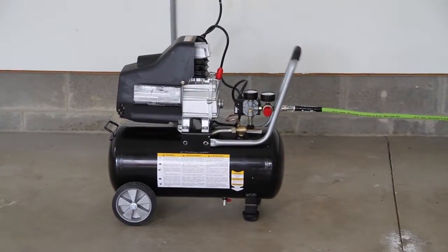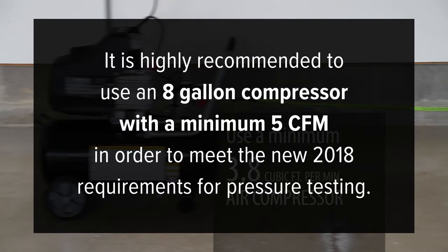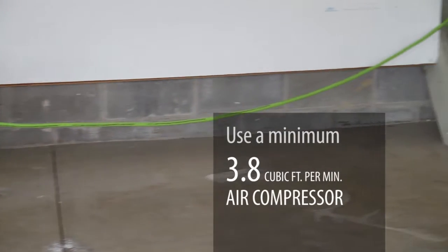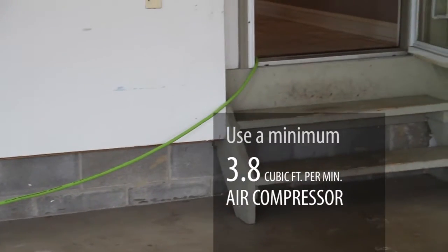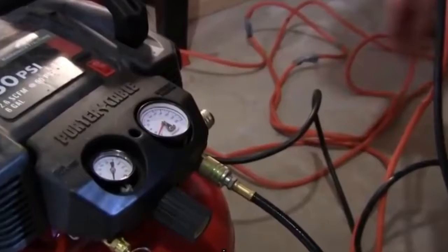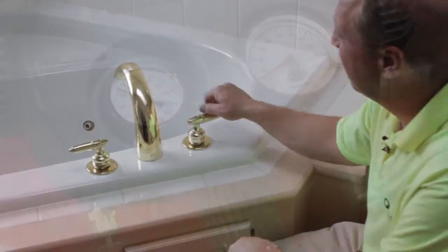All lines must be blown free of water, using a minimum of 3.8 cubic feet per minute air compressor. To blow the lines, hook up the compressor to an outside hose spigot or a laundry hookup. The compressor needs to be fully charged and all faucets and/or valves should be in the closed position.